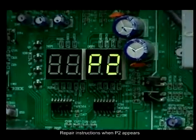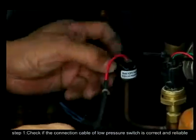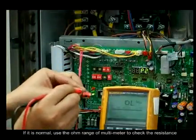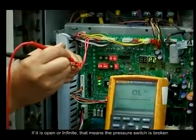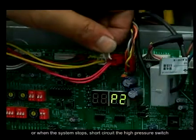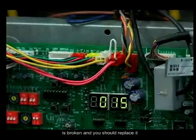Repair instructions when P2 appears. Step 1. Check if the connection cable of the low pressure switch is correct and reliable. If it is normal, use the ohm range of a multimeter to check the resistance. If it is open or infinite, that means the pressure switch is broken. Or, when the system stops, short-circuit the low pressure switch. If the malfunction disappears, that means the pressure switch is broken and you should replace it.